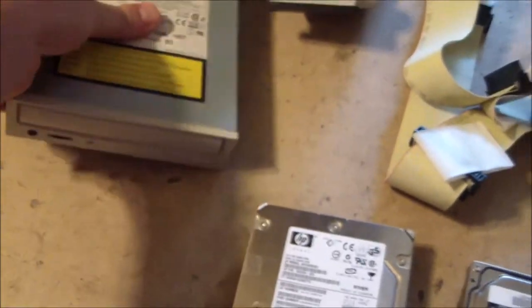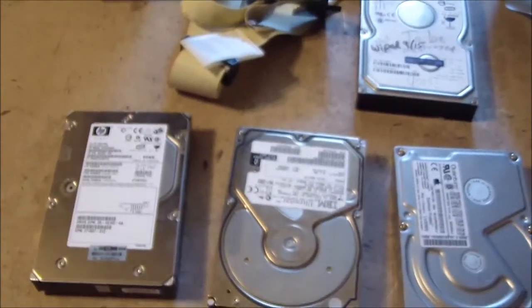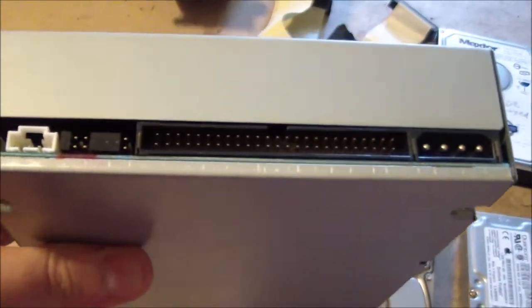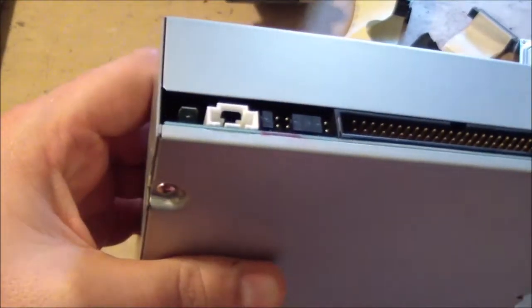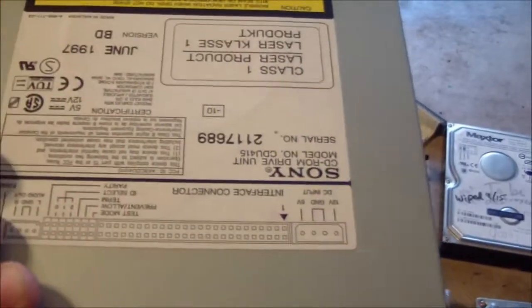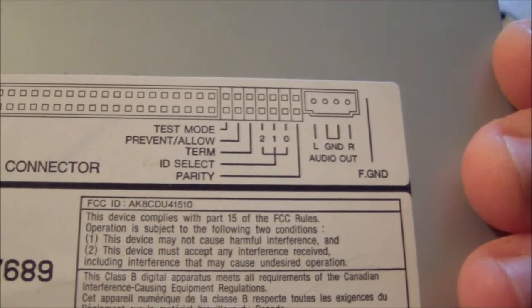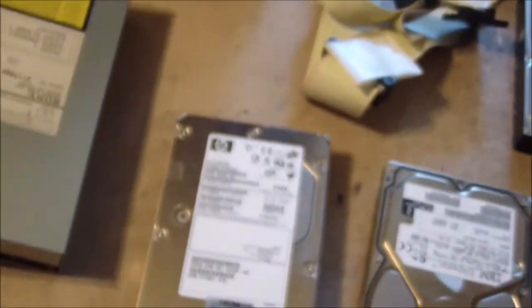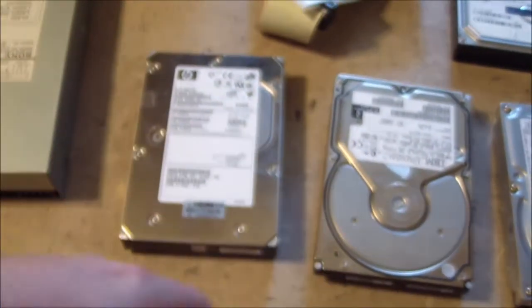And then we have, this is a Sony SCSI CD-ROM drive. It uses the 50 pin, and it pretty much looks the same except for all those extra jumpers, for setting the device IDs and things like that. I believe it tells you on here what they do. You can only set this ID 0, 1, or 2, but it has a couple other options there. All right, so let's take a look at one in action, and then I'll show you one that has all kinds of SCSI stuff set up on it.